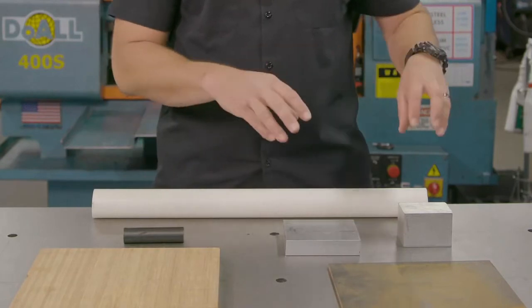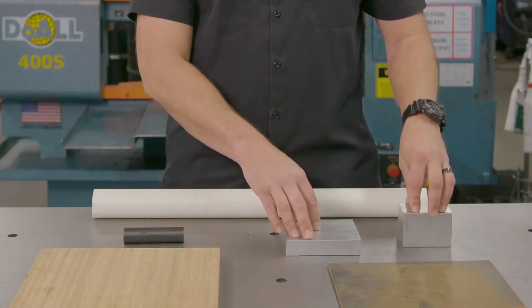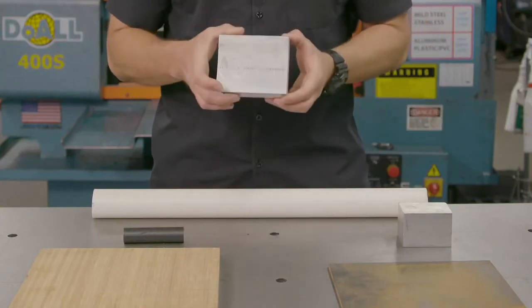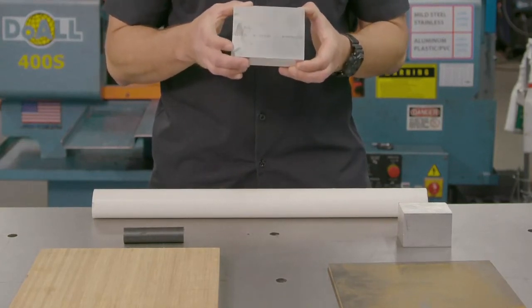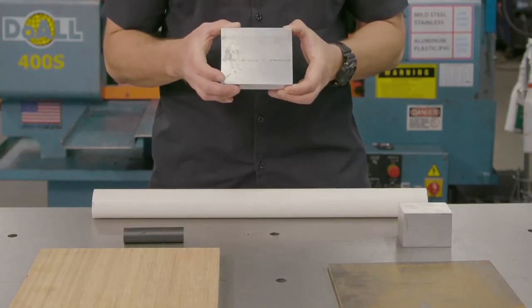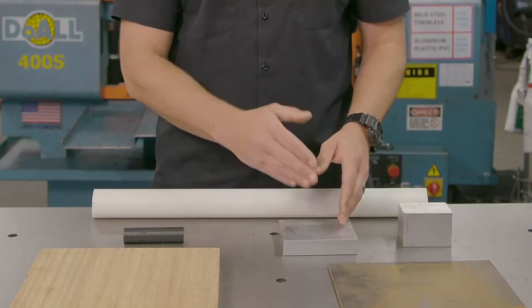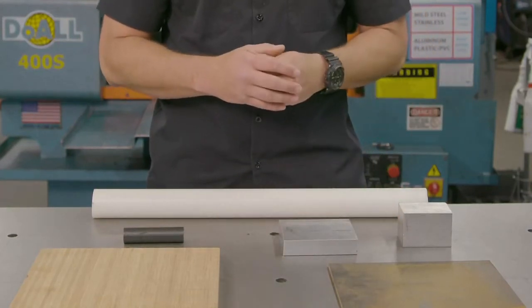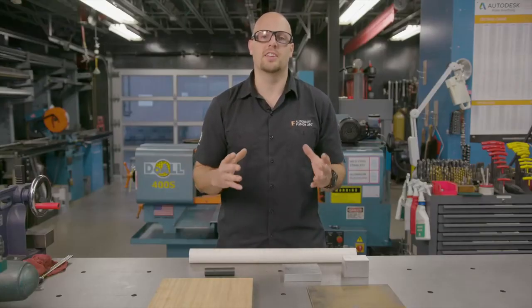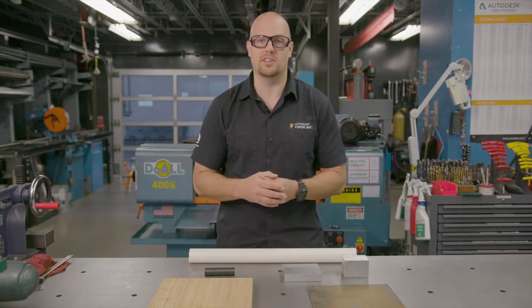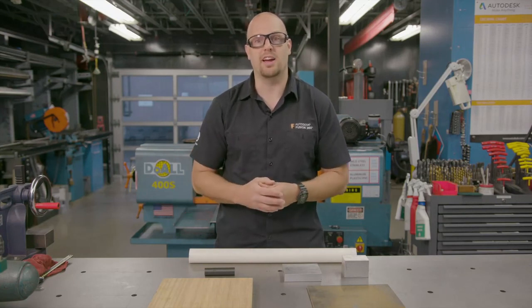What you'll find is that even in the same family of materials, take aluminum for instance, there will be different machinability levels. What we've got here is 6061 aluminum. 6061 aluminum comes in multiple grades depending on whether it was annealed or heat treated, and those grades are going to change its machinability. And then even going from 6061 aluminum to 7075 aluminum will change the machinability of the material. So all of this is stuff that you need to keep in mind when you're initially designing your part, to make sure that the part can be made properly on the equipment you have access to when you're done.